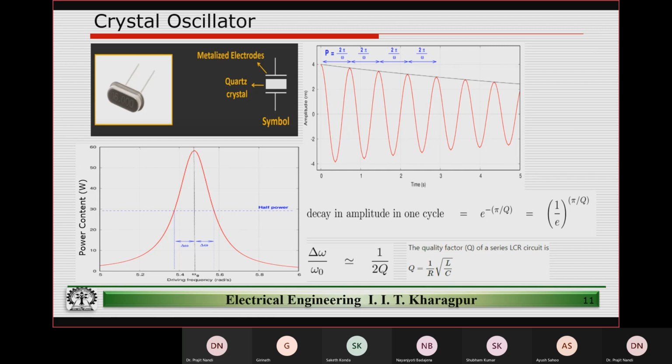That is understandable because of this 1/R, you're losing energy in the resistance of the crystal. Somebody has to supply that energy back, so that has to come from the battery, from the circuit that you have designed. That is another way of understanding that you'll be consuming more power if your quality factor is poor. Is that clear? I have not written that down, but is that clear?